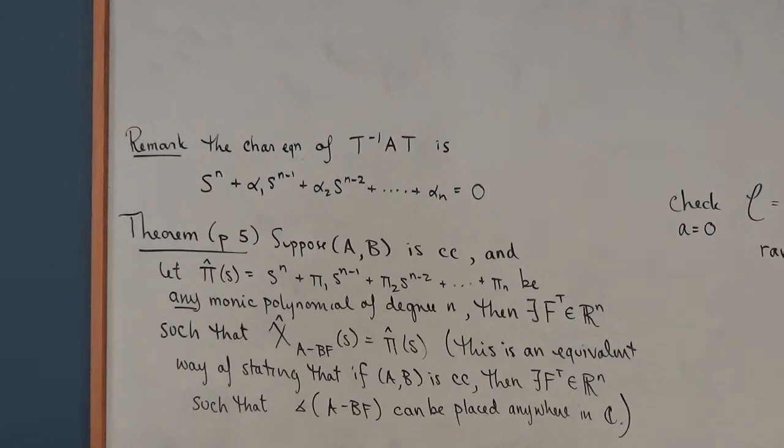We haven't spent a lot of time talking about zeros, but you can take a look at the overall effect of what that feedback matrix F is doing to the overall transfer function of your system, and then look at the response. So what you can do in frequency domain, you can also do in the time domain here. The algorithm that I showed you, we're not going to go through it in class, but in lecture notes 21, the multi-input, multi-output algorithm is just one example of how you might use the extra degrees of freedom in F, when you have more than you need, for design.